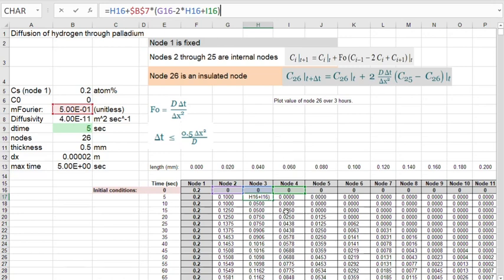That's the other thing with the formula. Just notice that I'm looking here at node 3 at 5 seconds. Okay, and then my formula is looking at the previous time step here at 0 seconds. So it's looking to the left, center, and right of the node that I'm interested in. So that's true of any node I click on. So if I look at this one, it should be looking up here at the previous step. Okay, so there it is. So that's one double check just to make sure it's looking at the previous time step, left, center, right.